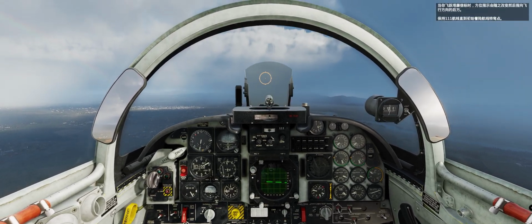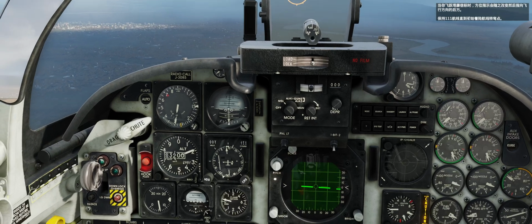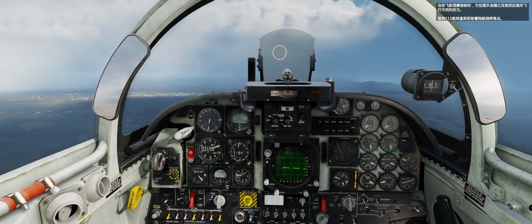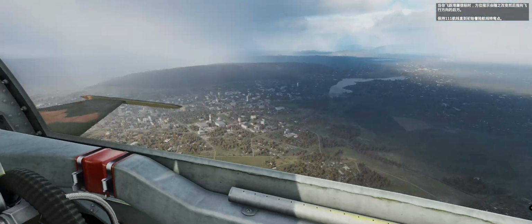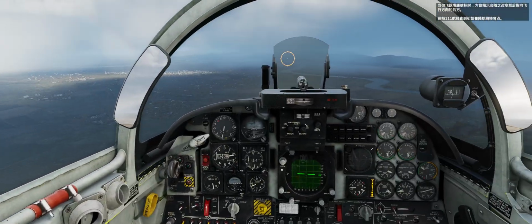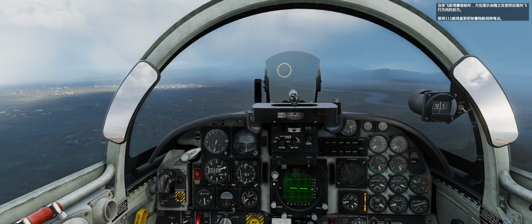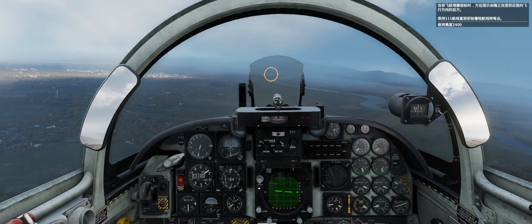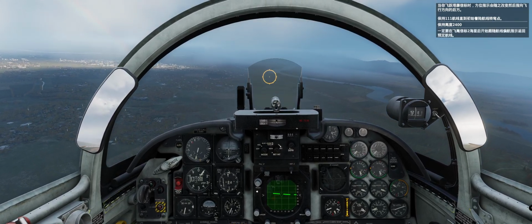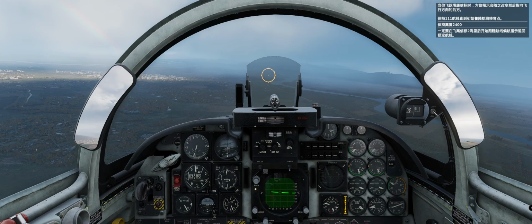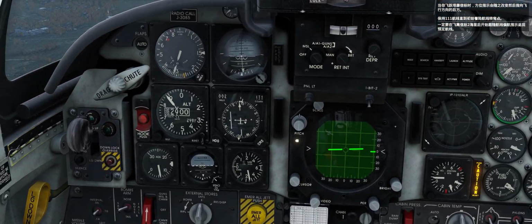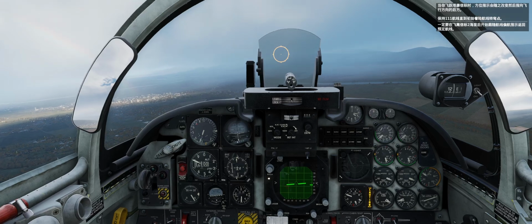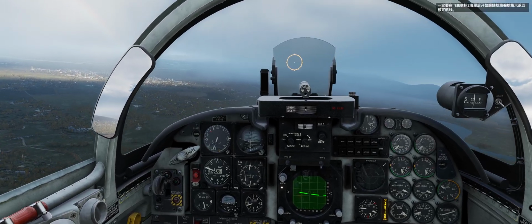The bearing pointer changes its position, flips backwards, when you fly over the TACAN beacon. Follow a course of 111 degrees to your initial landing course turn. Fly 2 miles away from the beacon, and only then start following the deviation bar to return the aircraft to the desired course.